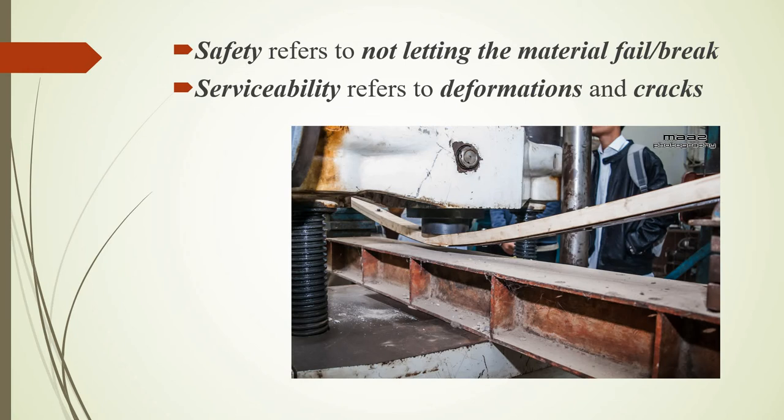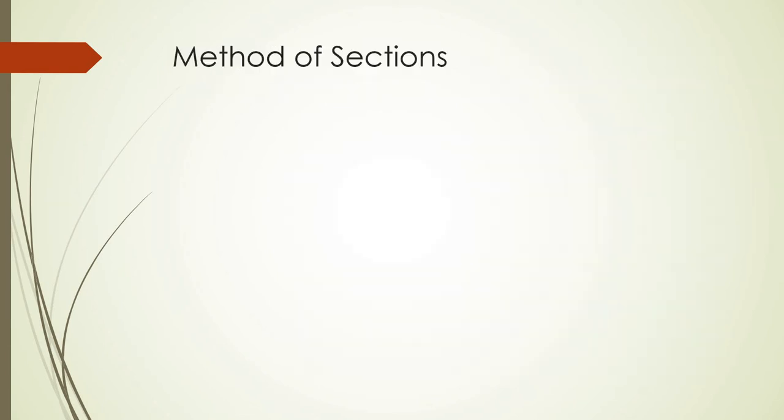You can see large deformation in this particular beam when it's being tested, and formation of a crack at the center as well. So when we refer to serviceability, we're talking about excessive deformations and crack formation. If something is meant to be serviceable, it should not deform much and should have fewer cracks.